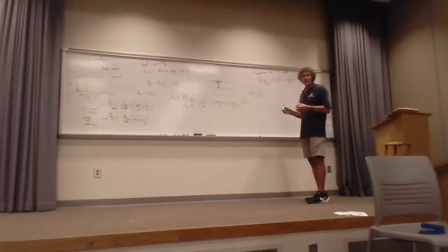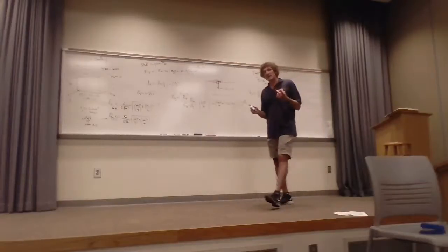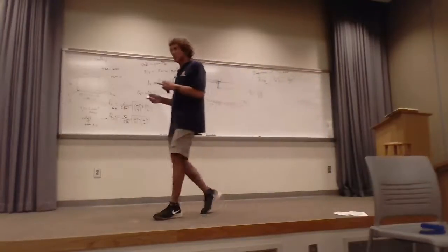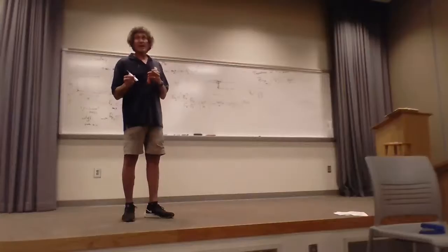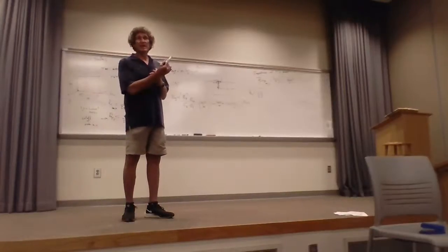Next thing is velocity on a guide, right? So there's 2 types of velocity. There's phase velocity and there's velocity of energy. And in a waveguide, as you get close to cutoff, the phase velocity goes to infinity. But the velocity of energy goes to 0.